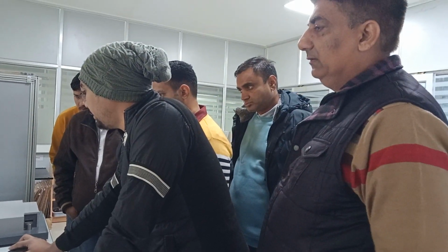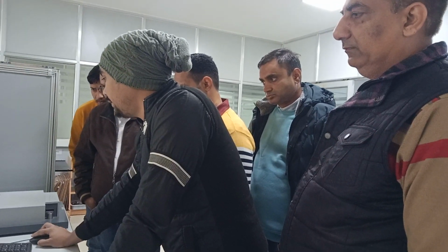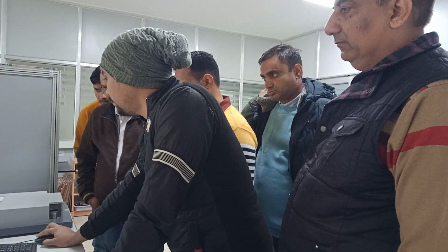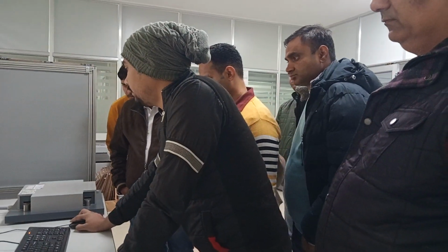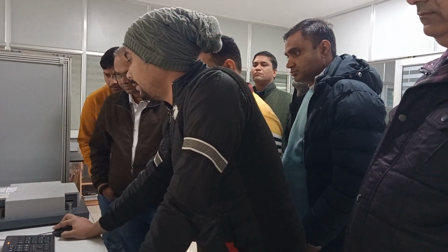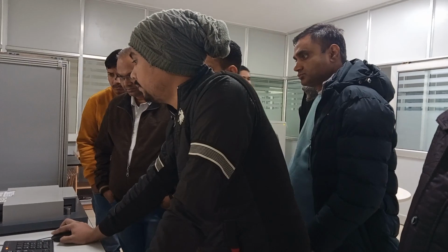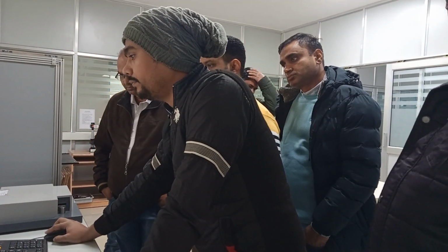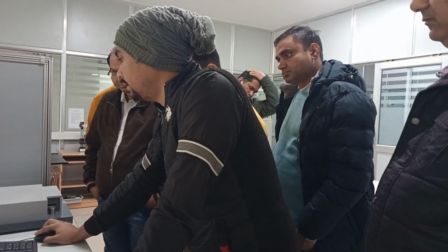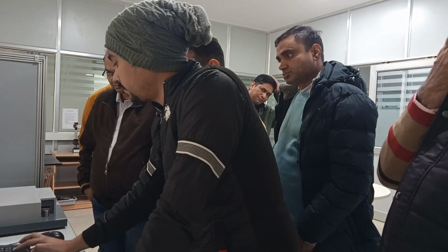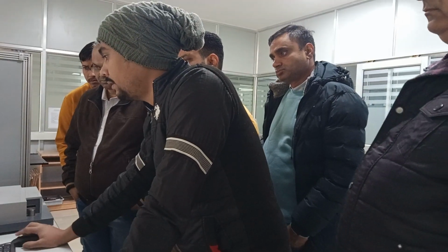That sample is 425 milligrams, density 7650, geometry length 499.95 mm, width 499.91, thickness which we are observing is 0.28. Number 1 is SST, a single sheet tester. And the cross section is calculated automatically by the software. We are measuring the losses at 1.5 Tesla, 1.7 Tesla. Now we also observe the magnetization and polarization.